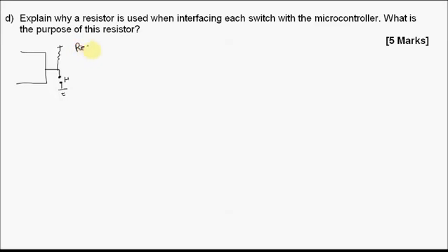So resistor pulls up pin and stops floating when button isn't pressed.